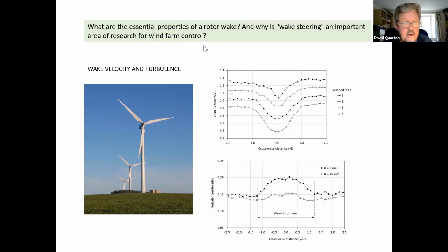One of my very first research projects when I got involved in wind energy back in the 80s was to bring together about 100 experimental data sets, some of them from wind tunnel tests, some of them from real wind turbines in the field, and pull together the turbulence intensity measurements that were made in a wake situation and try and make sense of them. What I did at the end of all that work was to pull together a kind of empirical characterization of the wake turbulence. And the formula that came out of that empirical characterization is in Colin's book.